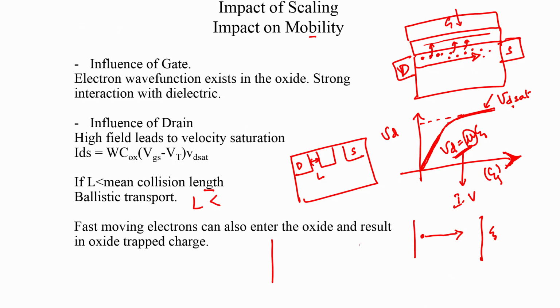But in a semiconductor lattice, the electron undergoes all these scattering events. It scatters with the lattice defects, it scatters with the lattice atoms, you have electron scattering, etc. And therefore, because of all these scattering events, we saw that the electron experiences an effective drift velocity, and as the electric field is increased, this drift velocity saturates because the electron is still undergoing these scattering events.